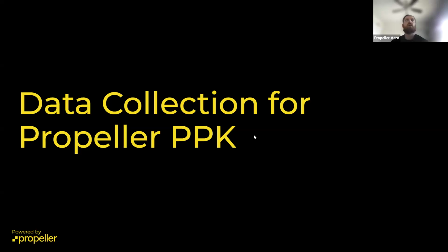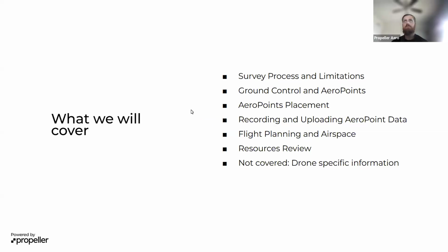All right, so data collection for a Propeller PPK, that's the post-process kinematic workflow. What we'll cover today are the survey process limitations, ground control and AeroPoints, how to place AeroPoints, recording and uploading AeroPoint data, flight planning and airspace, resources review, we've got a lot of those, and some drone-specific information. We will not be covering drone-specific information, sorry, because we can use quite a few different drones for the PPK workflow.